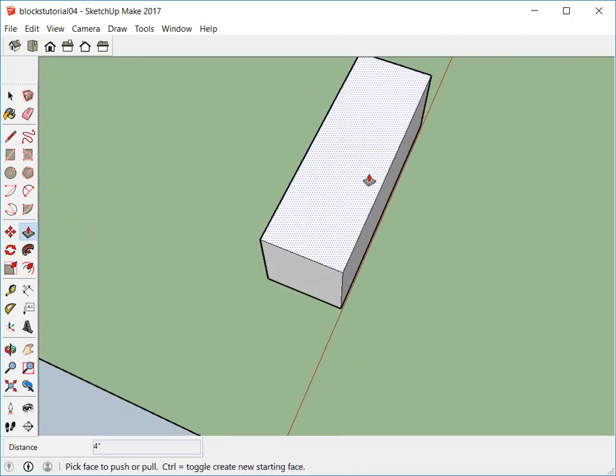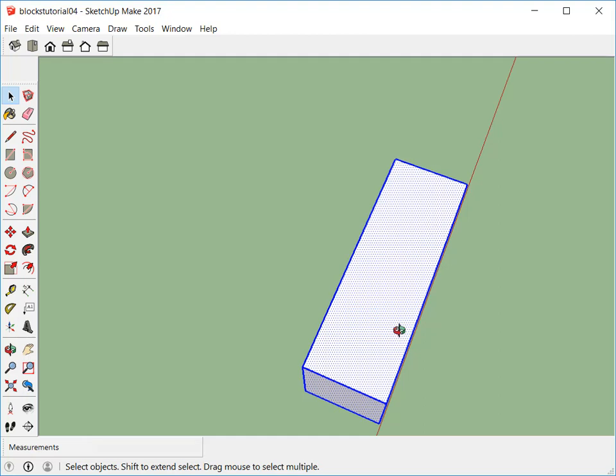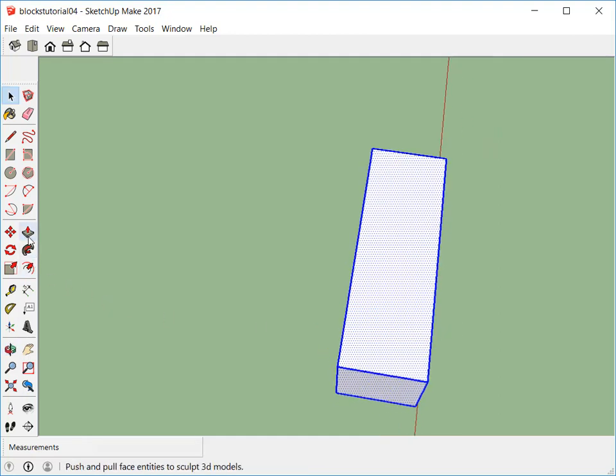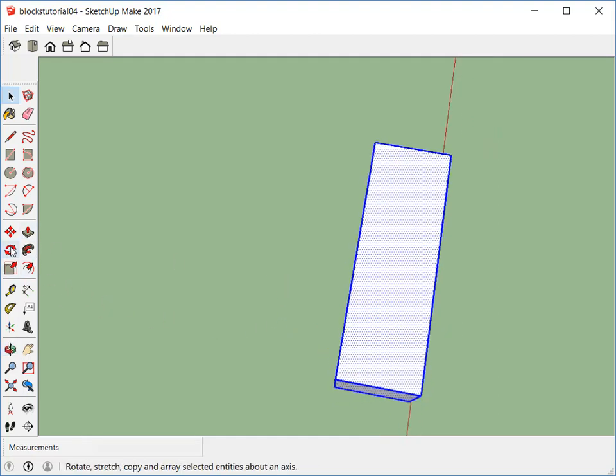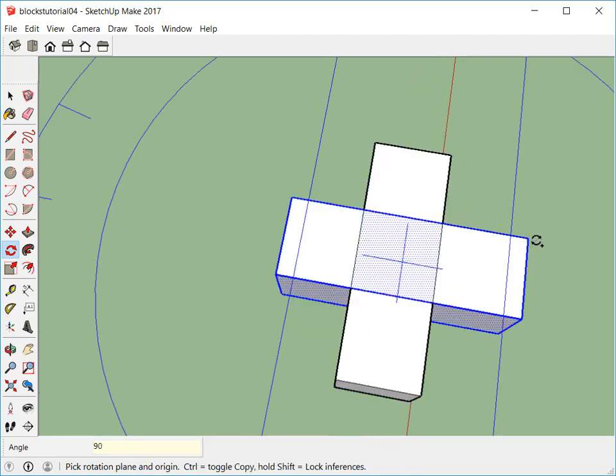We're going to rotate this and make a copy by 90 degrees. So I'm going to select all of this. Going to get the rotation tool. And I'm going to need to rotate around the middle. So I'll get the midpoint of one, and the midpoint of the other side, and where they meet is where I'm going to click. And then I get to draw an arm, hold control, and you get a duplicate, type in 90, and that's the other one.